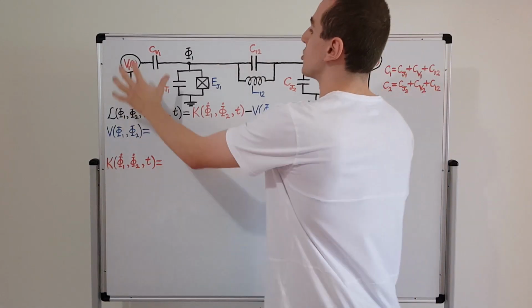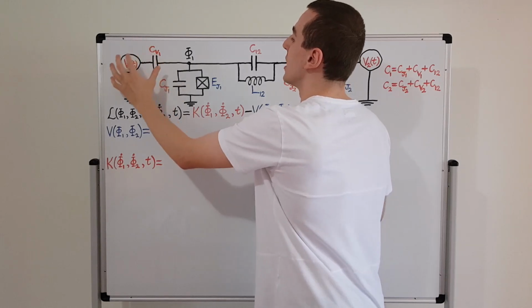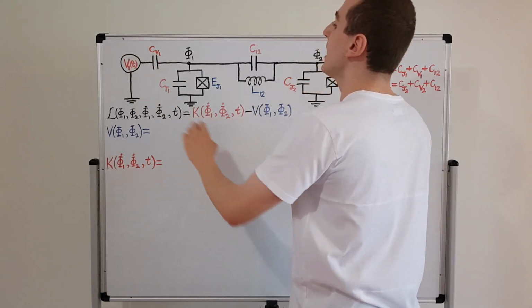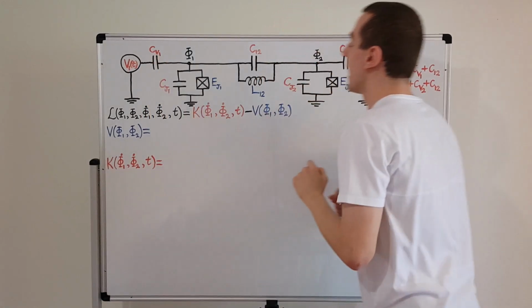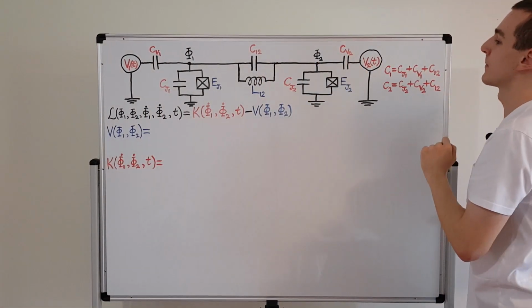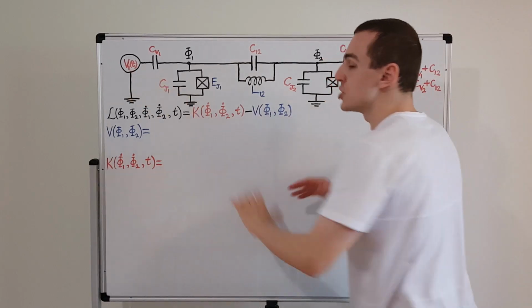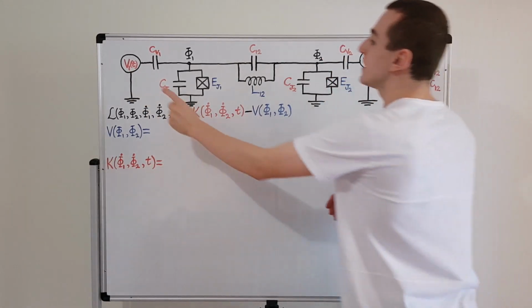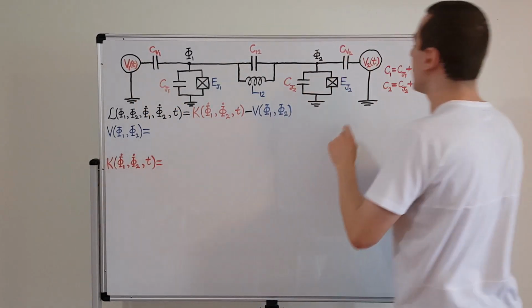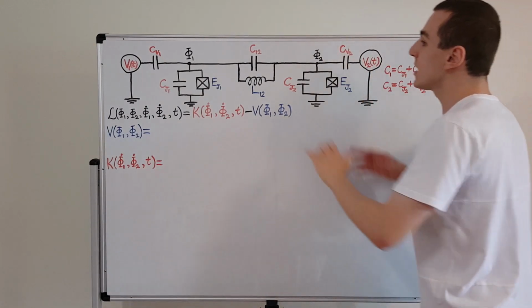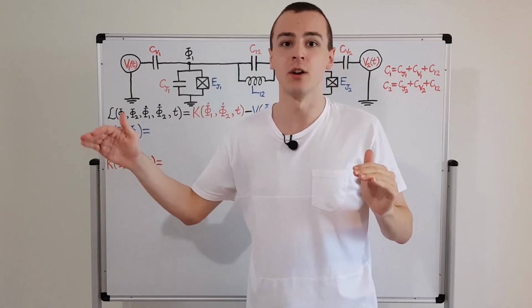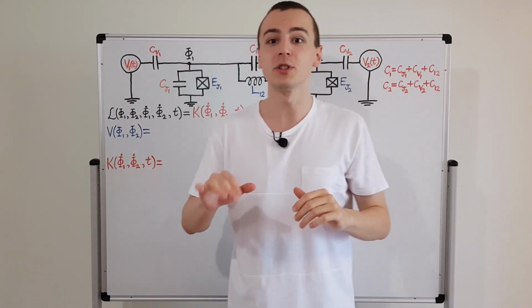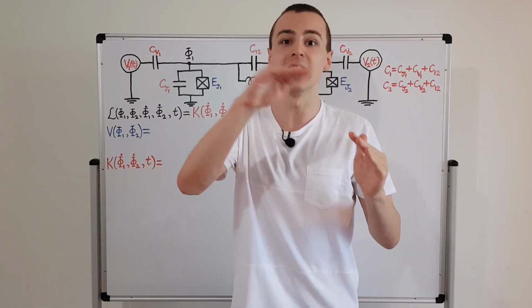And these sources of voltage, these external driving voltages, are coupled capacitively with a capacitance labeled CV1, and over here we have CV2. These voltages are in general time dependent. So I've explicitly stated that this is a function of time and this is a function of time. We can model these external voltages as cosinusoidal functions, or we could even multiply that cosinusoidal function by a Gaussian envelope.